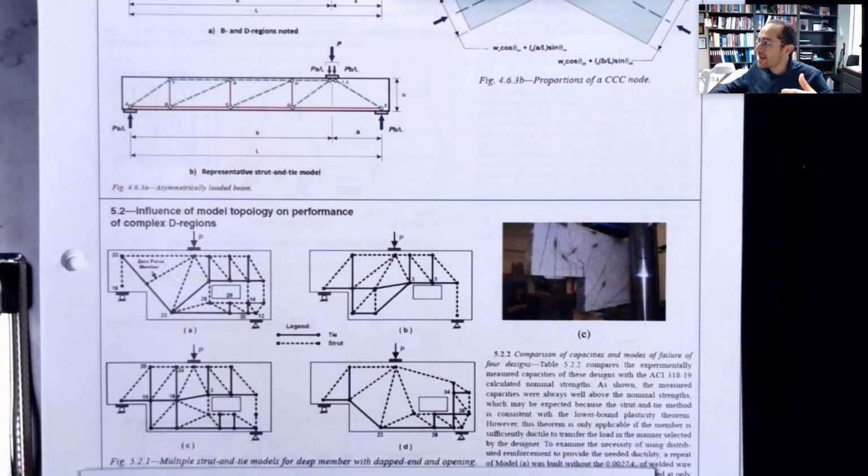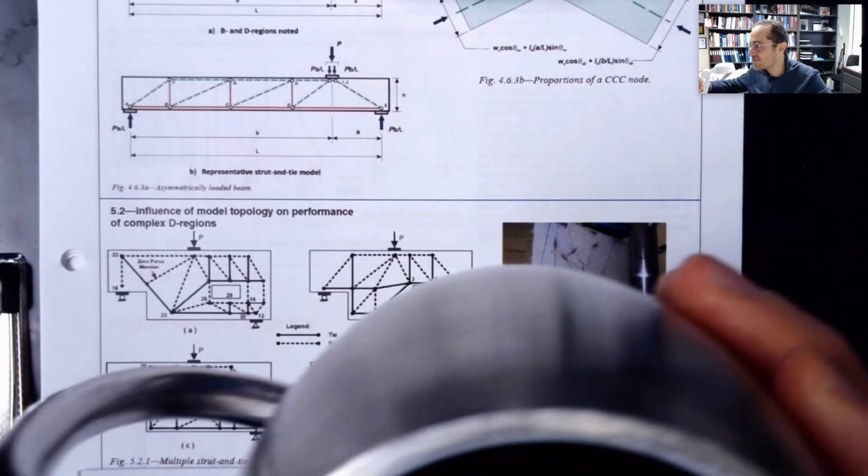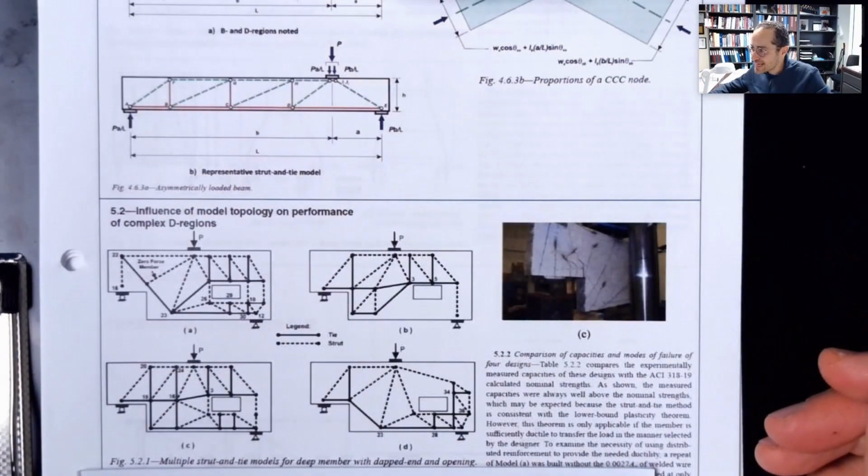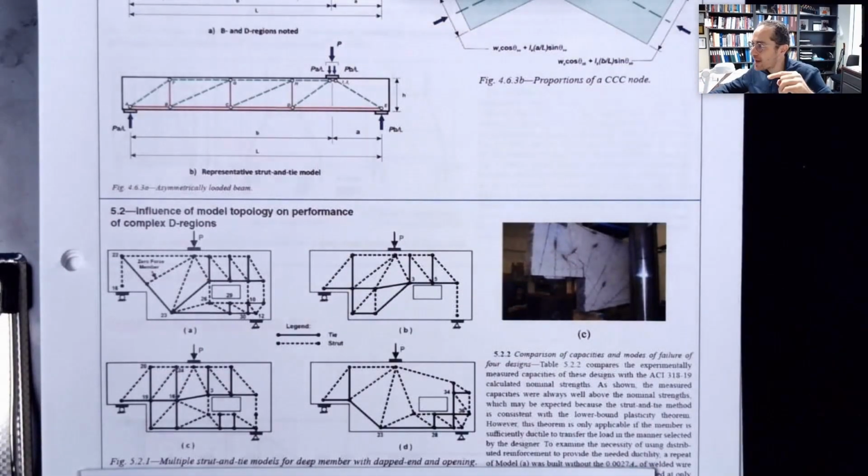If you look at A, you see some crazy diagonal ties, so you have to put in that reinforcement. It's going to be a major difficulty because you need to extend the bar diagonally, then another diagonal bar, and more than likely you would get a call from the contractor asking for modifications to your design, and you would have to redesign. Let's look at the experimental results.